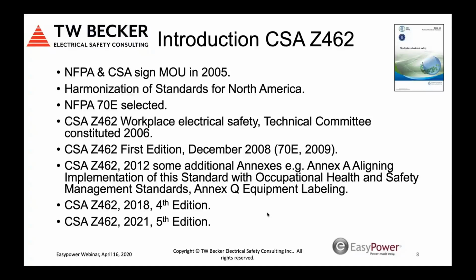There was a rule in the National Electrical Code, Article 110.16, with respect to arc flash labeling on electrical equipment, and that information became known to members of our Canadian Electrical Code Part 1 Tech Committee, and we were going to have a new rule that wasn't included, which is an arc flash and shock equipment label. So our label includes the word arc shock on it. And then in 2006, that was published in our CE code.